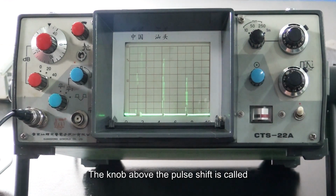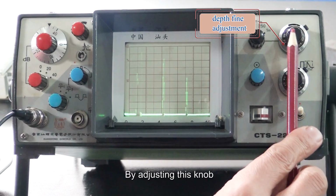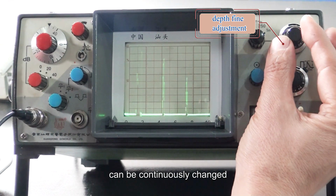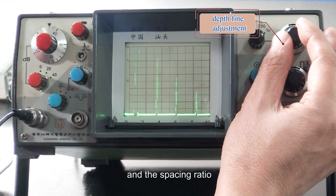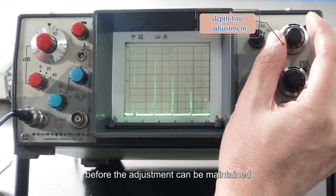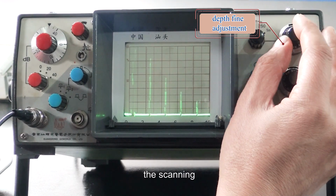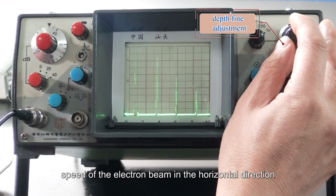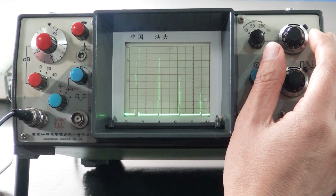The knob above the pulse shift is called depth fine adjustment. By adjusting this knob, the spacing between all echoes on the display can be continuously changed, and the spacing ratio before the adjustment can be maintained. The scanning speed of the electron beam in the horizontal direction is actually changed in the instrument.